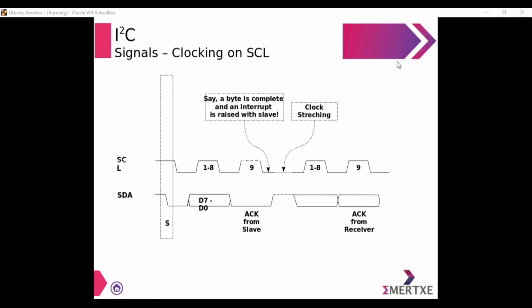Okay. Can the slave also transmit on the bidirectional data line? Yes, the slave can also transmit. Previously, we saw the example itself, right? The RTC was transmitting the data from the second register. So the slave can also transmit the data. Understood what is clock stretching?